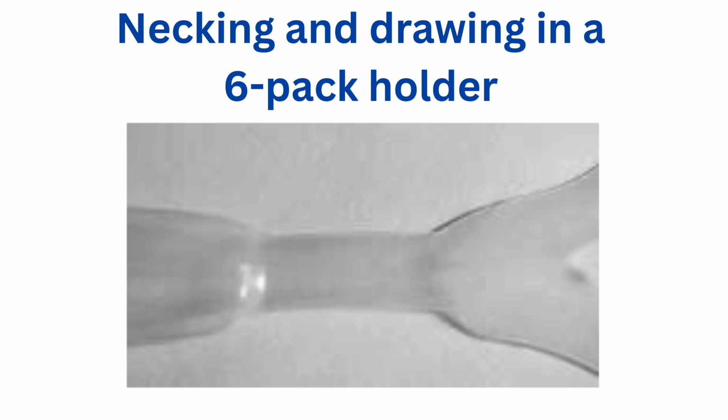This process can be observed without the need for a testing machine by stretching a polyethylene six-pack holder. Not all polymers are able to sustain this drawing process. It occurs when the necking process produces a strengthened microstructure whose breaking load is greater than that needed to induce necking in the untransformed material just outside the neck. During yield and the plastic flow regime following yield, the material flows with negligible change in volume. Increases in length are offset by decreases in cross-sectional area.